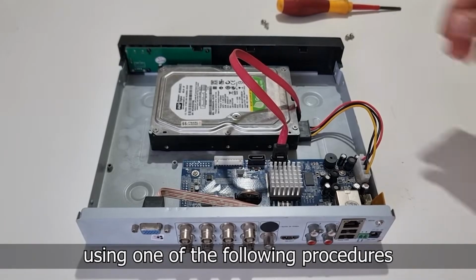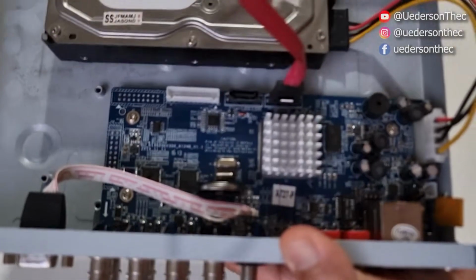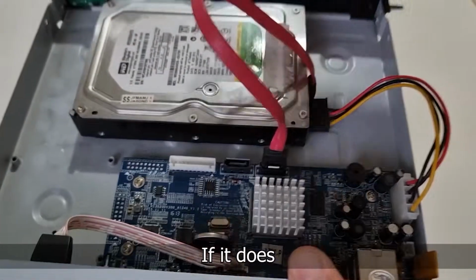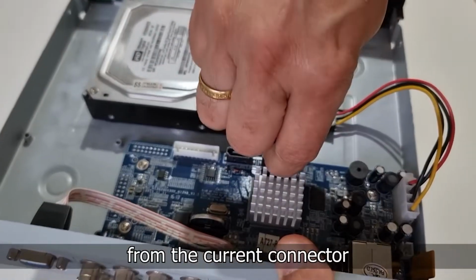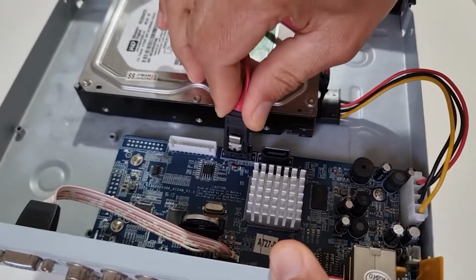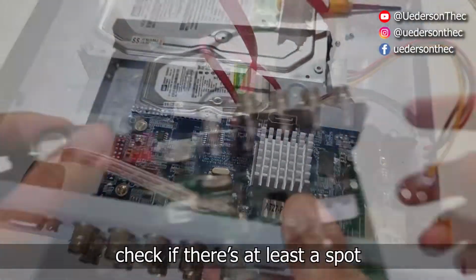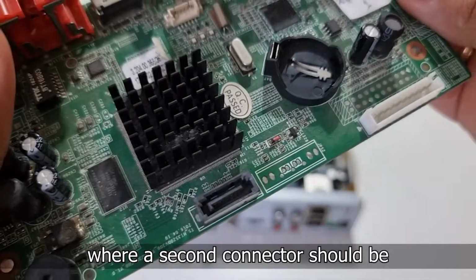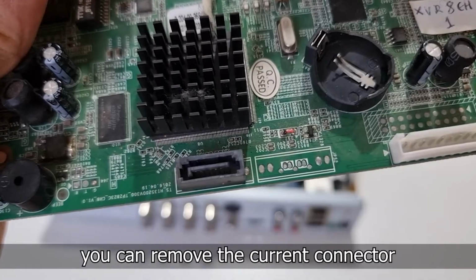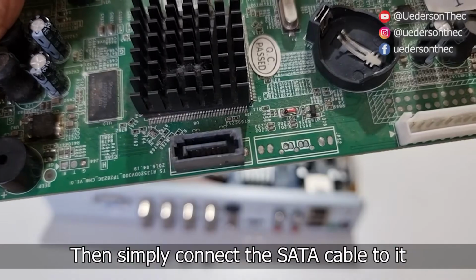First, check if your device has a second SATA connector. If it does, disconnect the SATA cable from the current connector and connect it to the other one. If there isn't a second connector, check if there's at least a spot where a second connector should be. If there is, and you have experience with soldering electronic components, you can remove the current connector and place it in the second position. Then simply connect the SATA cable to it.